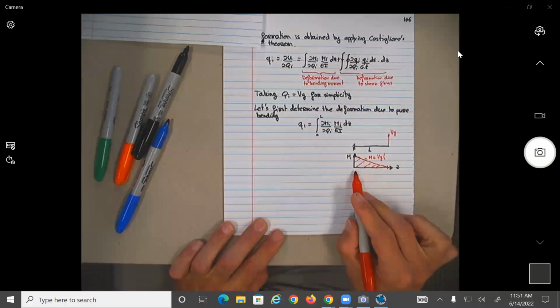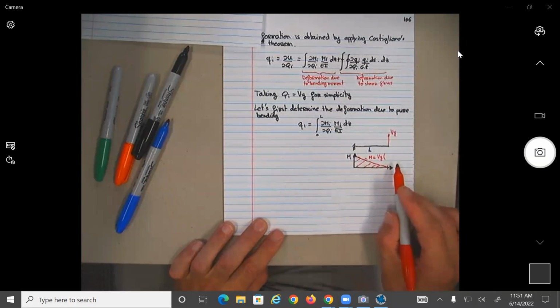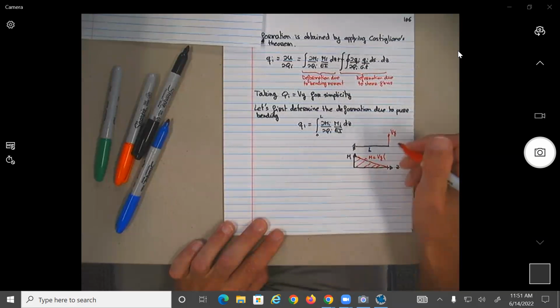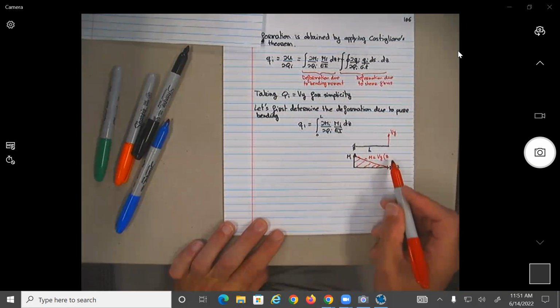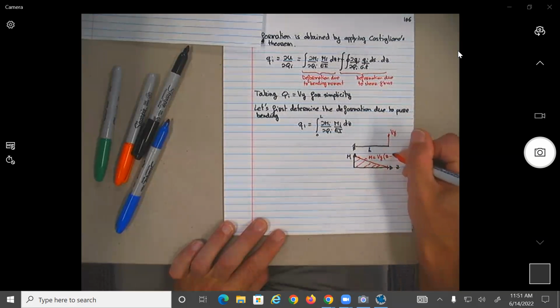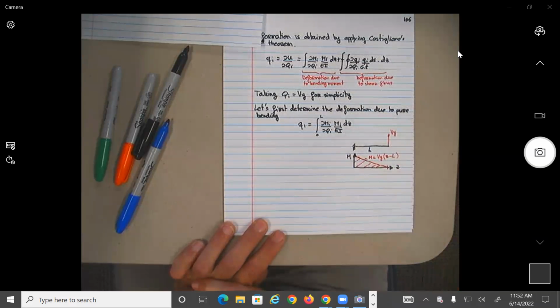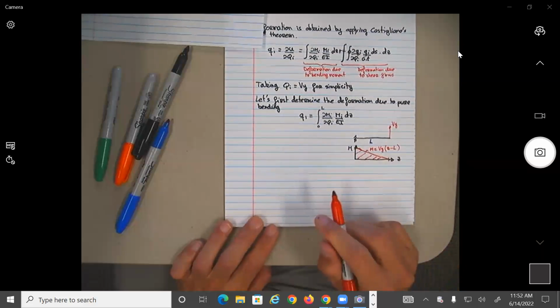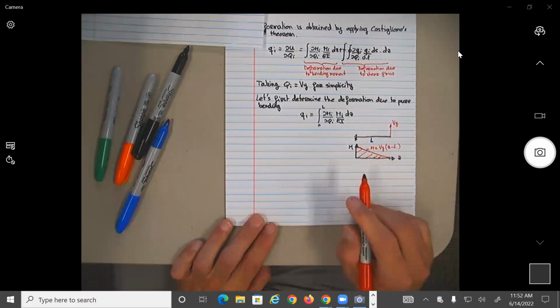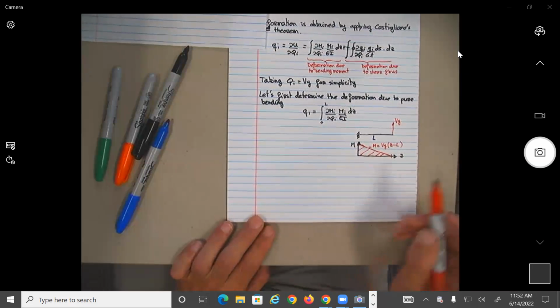If we start the reference frame here, in order to be 0 at the end, what should we put over here? Would that work? No, because it will be maximum at the tip. So in order to make it 0 at the tip, we should put minus L. You can put plus minus here; it really should be negative, but it doesn't matter. At the end, it's not going to change anything, so it's fine if we leave it as positive.